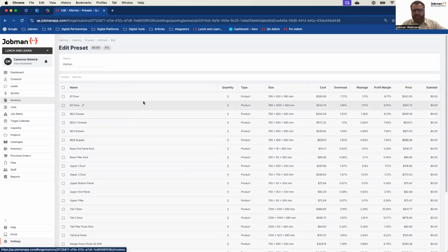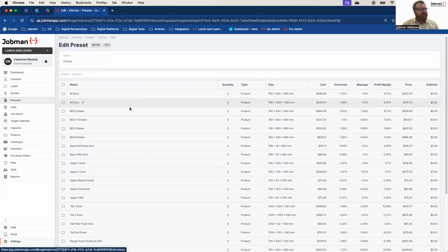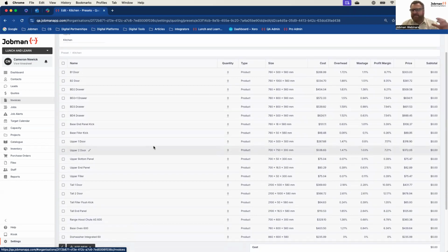Now, one recommendation I will make, there's a lot of information behind a preset. So each of these presets obviously has a product, and so that product is components which are linked to parts, which are linked to style items. So my recommendation is don't make these too massive. Like don't try and make presets which have every inclusion. It's a bit like an Excel spreadsheet where you've got 2,500 lines. Like you spend all day scrolling up and down, and loading times will be impacted simply because it's so much information. Try and concentrate on the majority. Keep these nice and tight and small but usable, and you will find they will serve your company extremely well. Having about 10 or 20 items in here is perfect.